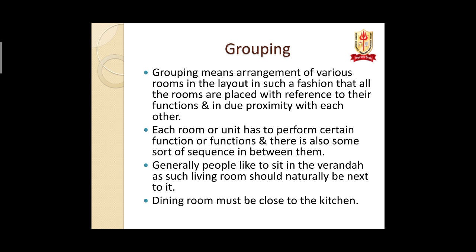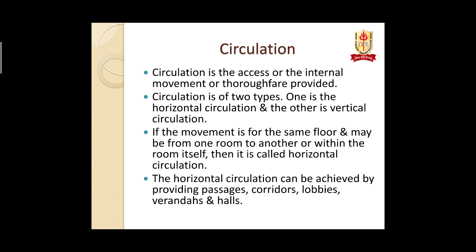Obviously, grouping means we have to group some rooms with each other so that their functions match with each other. Like this, we also keep the WC and bath side by side so that the trap pipes or water pipes can be arranged side by side. Like this, we arrange the rooms according to their function so that they can function smoothly. Then the next part is circulation.